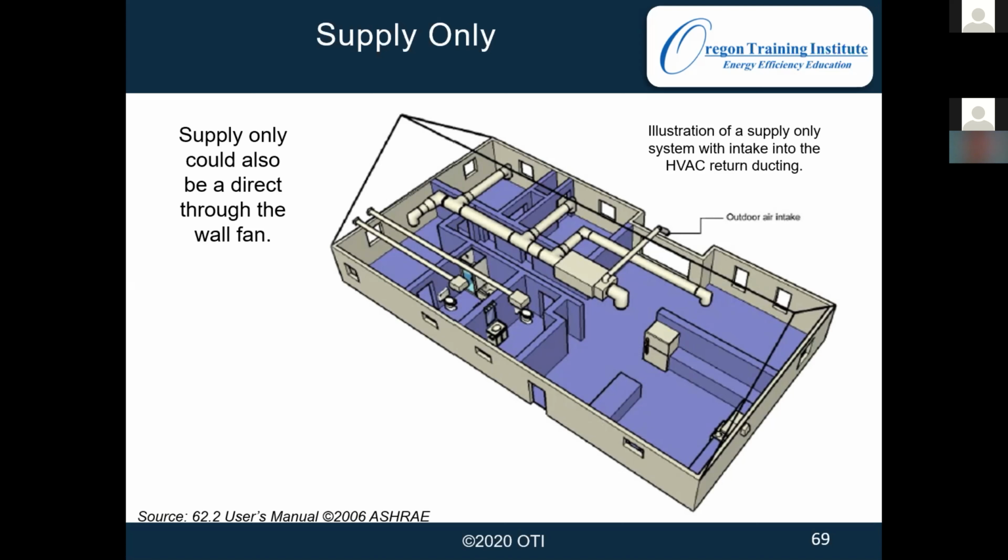And if we want to use this in our ASHRAE calculation, we're going to have to measure the flow through that little fresh air intake, which is going to be difficult, as we won't be able to use our exhaust fan flow meter on that. We would have to use a flow hood or pitot tube to measure that flow. But most people aren't trying to meet ASHRAE this way, but it can be useful in solving backdrafting issues.